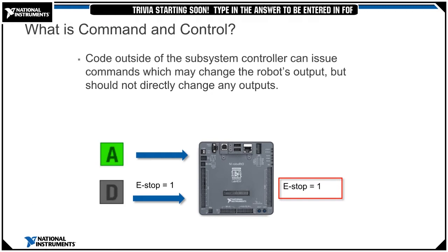I can make game relevant comments now. This is really exciting. But yeah, things like that can help you build these complex routines. For teleop, these same commands, go left, go right, pick it up, put it down, can execute asynchronously, which allows the robot to always be processing the latest driver inputs, and if implemented properly, new commands will interrupt, allowing the drive team to quickly respond to changing field conditions while also taking advantage of automated commands and command sequences.